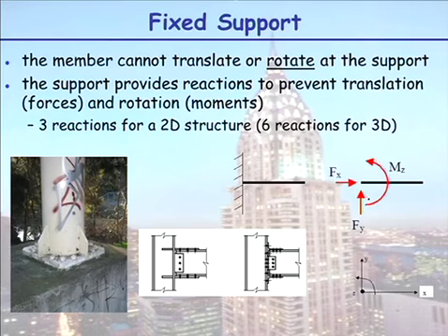When I try and rotate, the support applies an opposing rotation to any forces on the system. So the image you see here is the base of the truss footbridge going over Blackburn Road. If you ever want to stop and have a look at the base, you can see it's a nice thick plate, and it has 12 bolts holding the support column very securely to the concrete base.